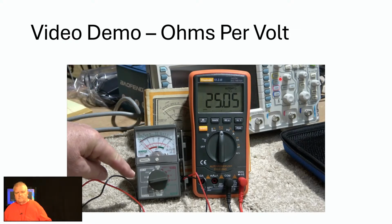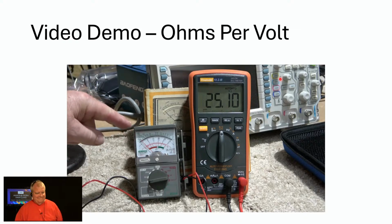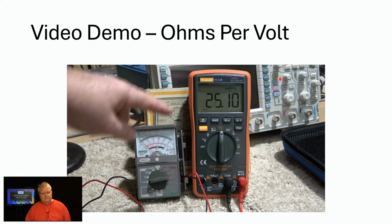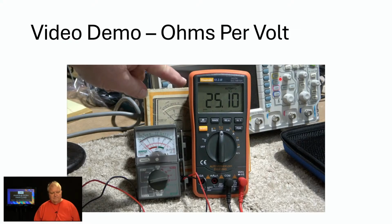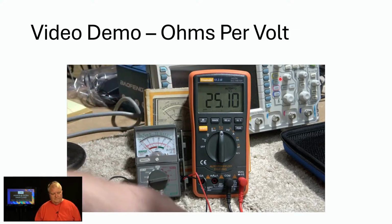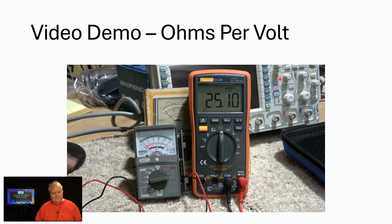So 2.5 times 10,000 gives you a loading of 25,000 ohms, as measured on my meter here to the right. We're connected from positive to positive, negative to negative, reading the resistors inside the meter. 25,000 ohms would load down a circuit considerably, so this is something that a technician has to keep in mind.